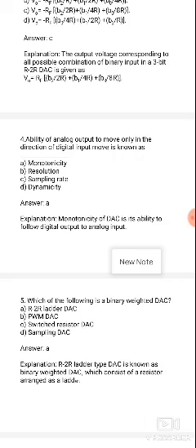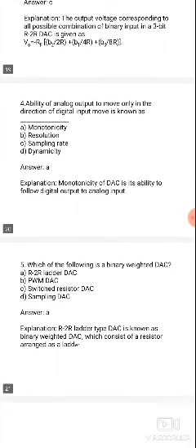It consists of an op amp, a V reference voltage and summing resistors. The binary inputs completely depend on the weights of the resistors, so maintaining the weights of resistors is also a main problem. To avoid the problems in binary weighted resistor, we go for the R-2R ladder network. In the next class, we will discuss the R-2R ladder network.